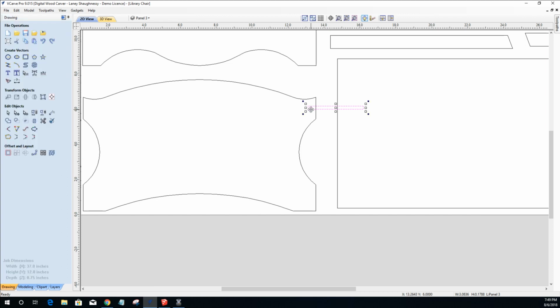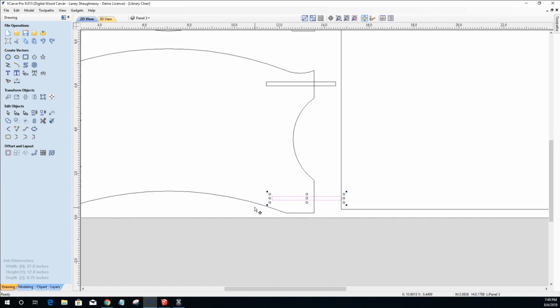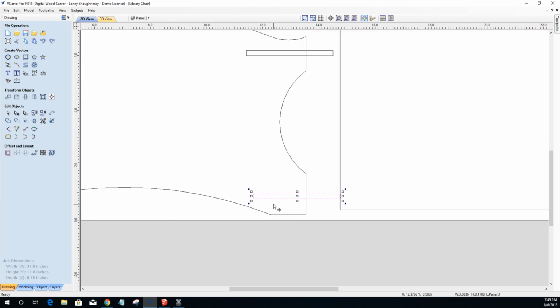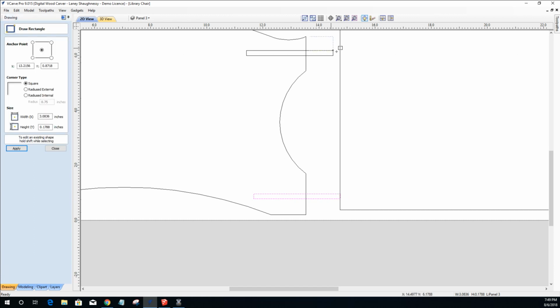So we've got 4 screws in each side, coming through these parts here. So whatever your design is, just make sure about the length of screws that you're screwing into, and they're going to be countersunk out of the chair side, because imagine that we have the chair part here that it's getting screwed into.